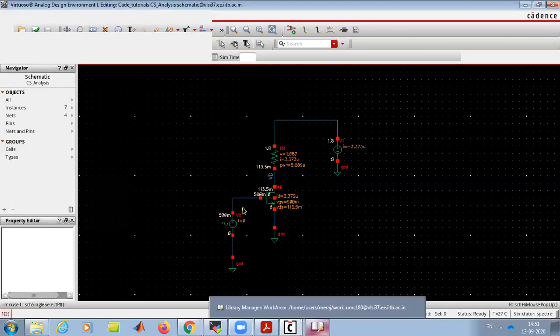There is a good rule of thumb that your signal should be more than 10 times your noise. So SNR of 10 is a good number. Otherwise you cannot figure out what is noise and what is your signal. If you use this amplifier for measuring ECG, electrocardiogram, from the body, what is the minimum voltage of an electrocardiogram signal?